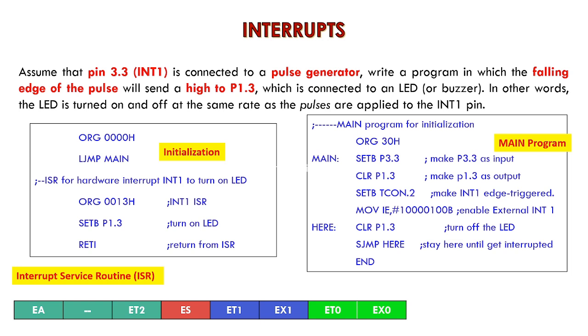Dear student, today we discuss the assembly language programming of 8051 microcontroller on interrupt based logic. The program given here is: assume that the pin 3.3, INT1, is connected to the pulse generator.